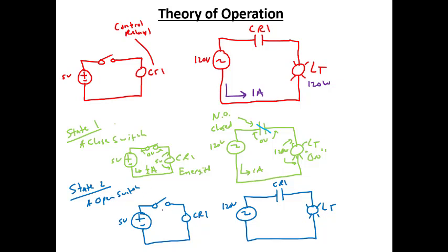So that means when we have an open switch, we'd actually see 5 volts across the switch. We would get 0 volts across our relay. Kirchhoff's voltage law always needs to apply. It's a law. So when we have an open switch, we get 5 volts across it. And we get 0 volts across our relay. This means that this is de-energized.